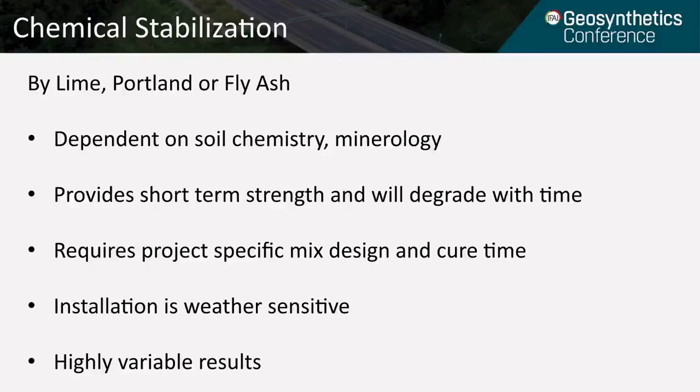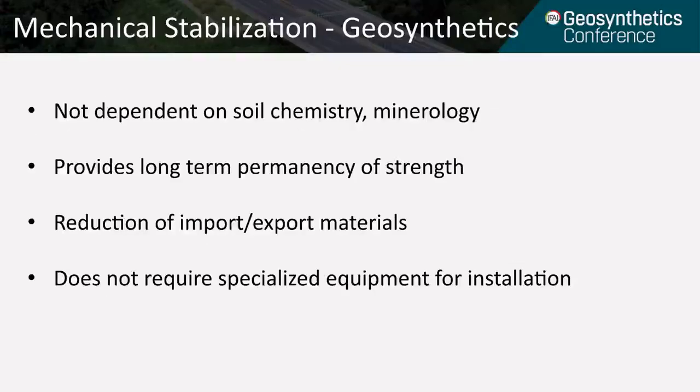And then, of course, for certain soil types, for example, sulfates that are present with lime stabilization, reactions between naturally occurring ground elements and the chemical additives could be detrimental to the durability of the stabilized platform. In addition, this method requires a unique mix design and cure time, and the results after all of that are still highly variable.